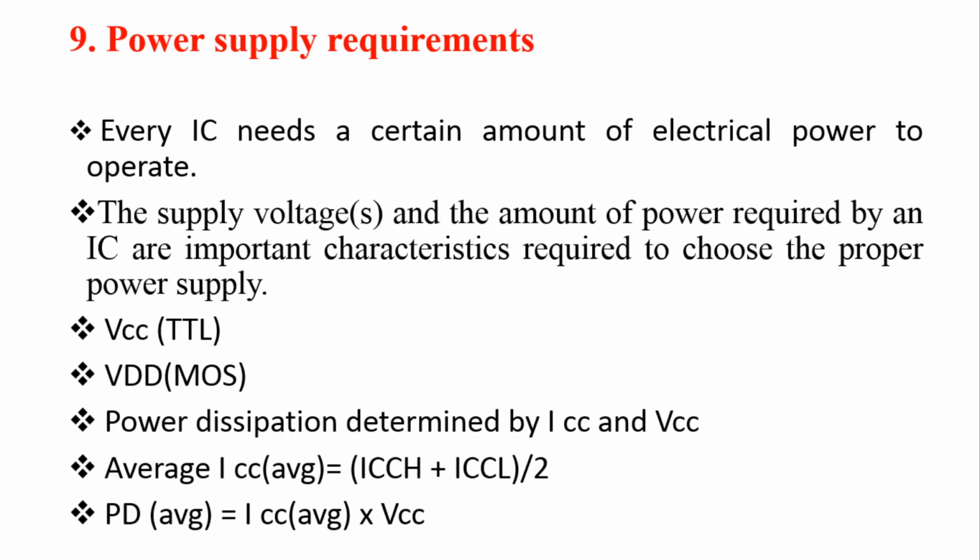The ninth one is power supply requirement. Every IC needs a certain amount of electrical power to operate. The supply voltage and the amount of power required by an IC are important characteristics required to choose the proper power supply. VCC for TTL logic and VDD for CMOS logic.